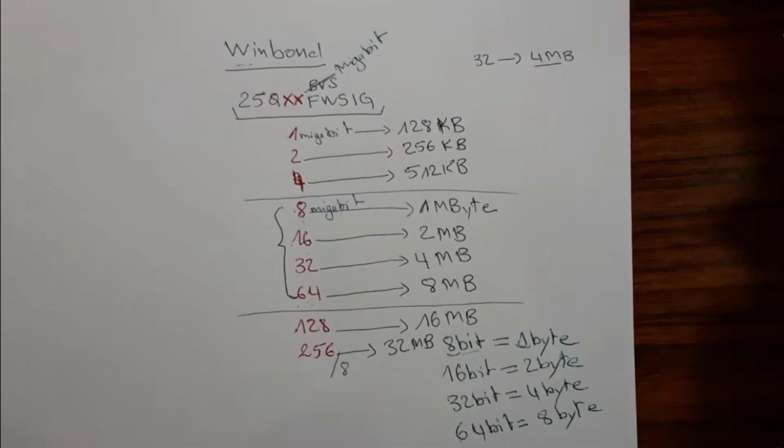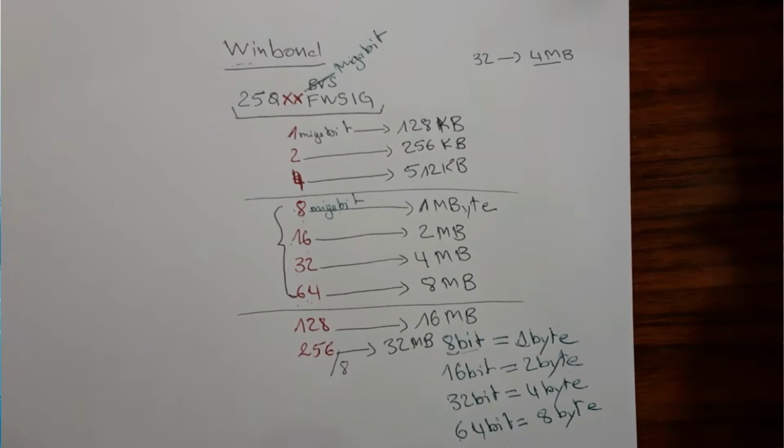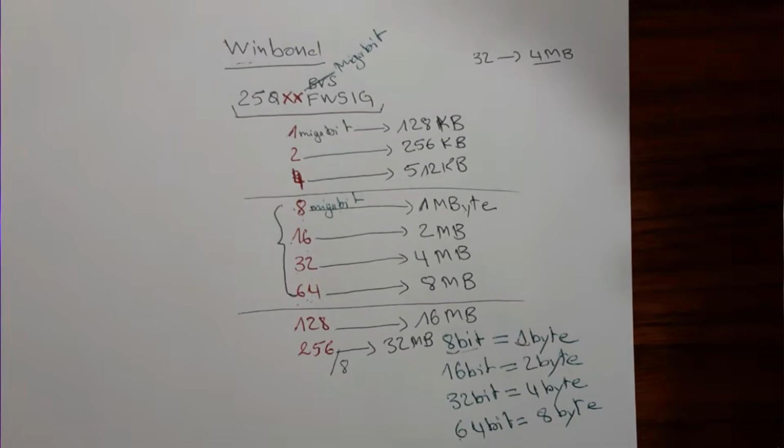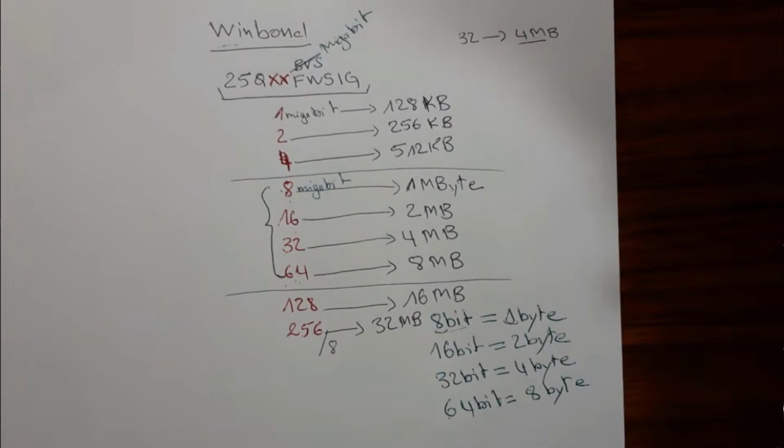So these are the main important tips you should know about BIOS sizes, because if you want to reprogram the BIOS, you should first know its size. When you know its size, you can compare it with the size of the flash file that you will use to program the BIOS.